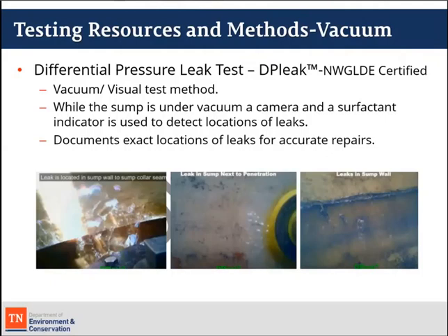If I could break for just a second. We have David McCamey. His concern is about valves to be removed from secondary piping. If the valves are not replaced or blocked, the hydrostatic test will fail due to liquid entering the secondary piping. Do you have any thoughts on that, or is that kind of a Don question?